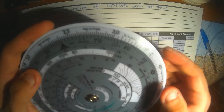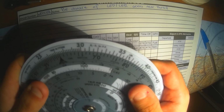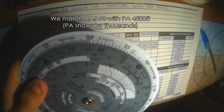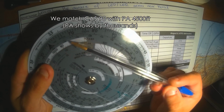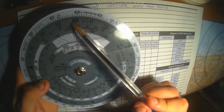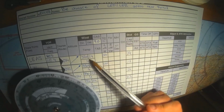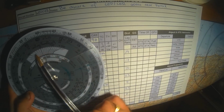We now take our CR3 instrument, or any similar you have, and calculate our true airspeed. We have to match our pressure altitude with the calibrated airspeed and then see what the TAS window shows, applying the temperature we previously discovered. We find our temperature and follow the line down to the TAS indication. Again, flying this low and this slow makes almost no difference between calibrated, indicated, and true airspeeds.